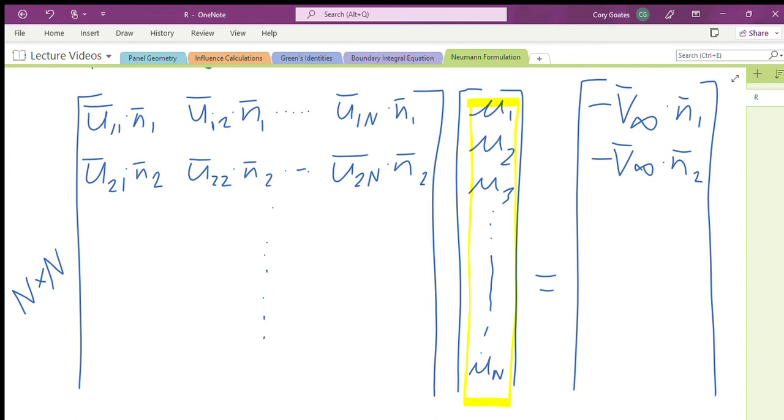It's really amazing to me that, in synthesizing an entire flow field, the whole thing boils down to just one matrix equation. And this isn't like CFD where the matrix equation is a gajillion elements by a gajillion elements. This is pretty small. In this class we'll be dealing with meshes that have maybe hundreds of surface panels. I hear these days that modern panel methods get up to hundreds of thousands of panels, but that's still not crazy. That's a tractable size of matrix equation for us.